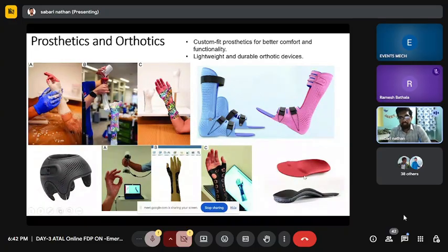But the problem is, if you want to reduce the weight, you need to go for this kind of structure. When you look at sports shoes nowadays, they have a lot of holes in the bottom, which gives a cushioning effect. But apart from the cushioning effect, from the mechanical and engineering perspective, a material with higher stress as well as higher strain is good. If you incorporate this lattice structure into a material with a higher strain rate, the strain rate will be good. So the flexibility will be high with the same strength.